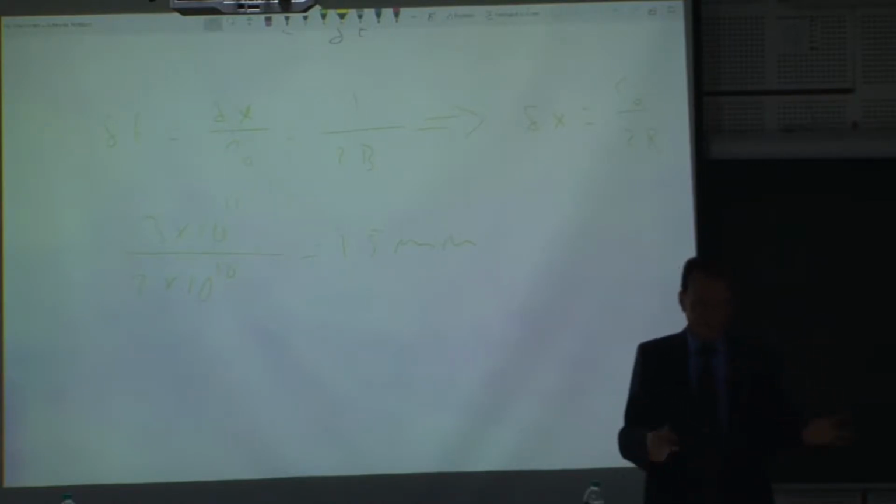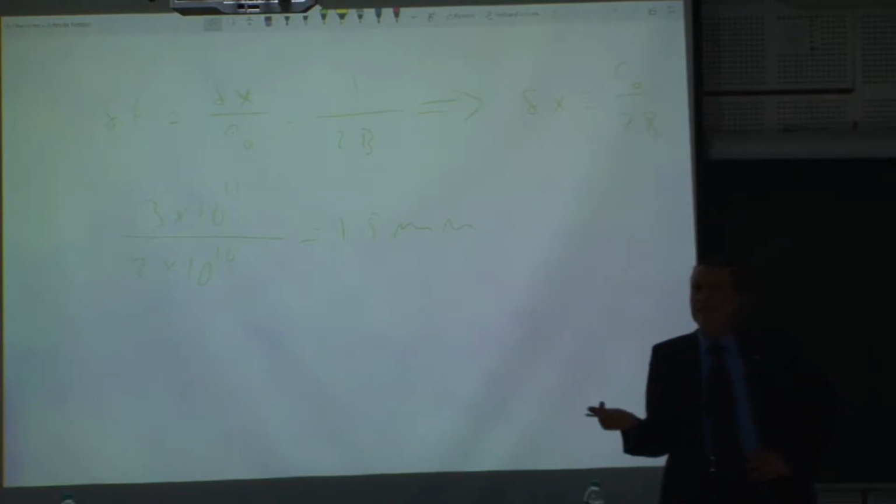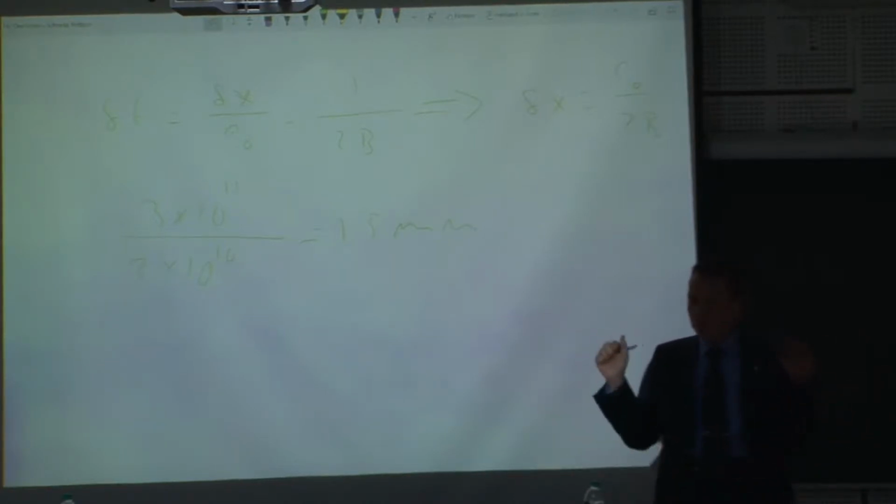charge carriers, whether it is holes or electrons, the flight time must be much less than a period. So that when it goes from source to drain, it sees as if it sees a constant field, so that it can react to the signal. Okay, and the flight time, irrespective now maybe of epsilon r of the gate or something like that, goes like c naught. So therefore, flight time is directly related to the physical length. So you can scale down, and you have a transistor principally,